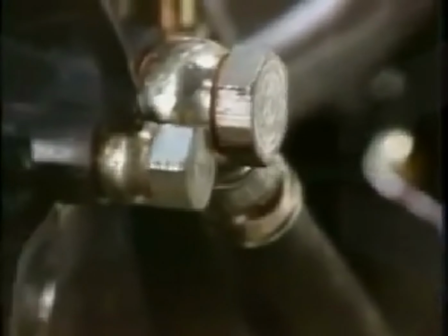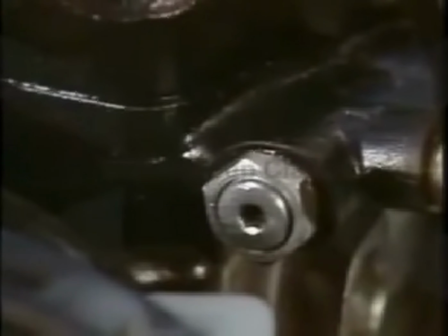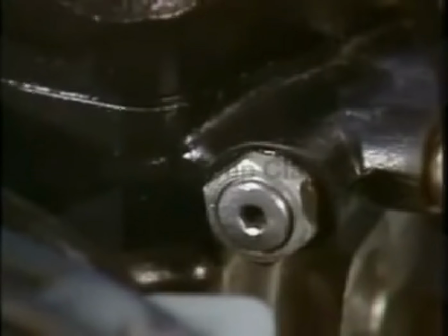The return pipe is kinked or incorrectly routed. The non-return valve in the fuel distributor could be defective. Or the warm-up regulator is defective.